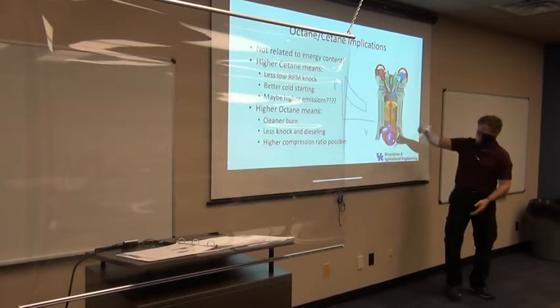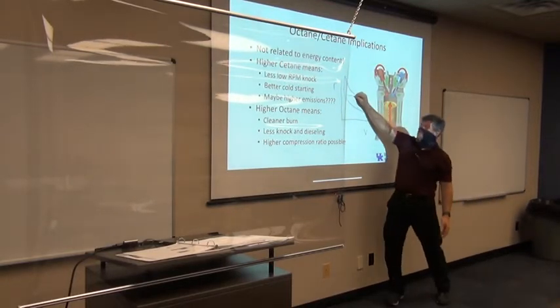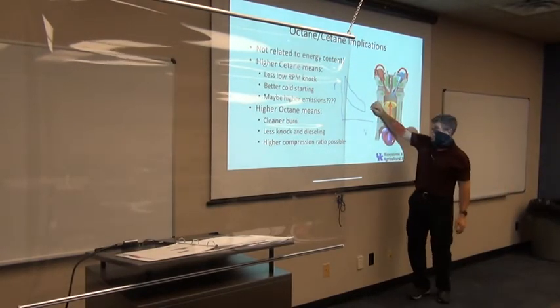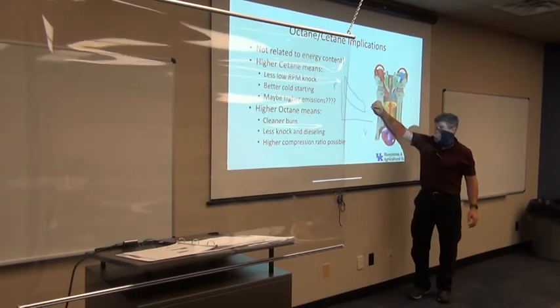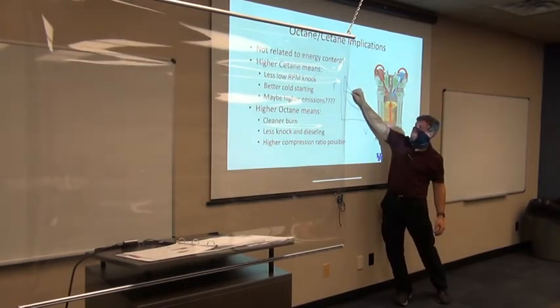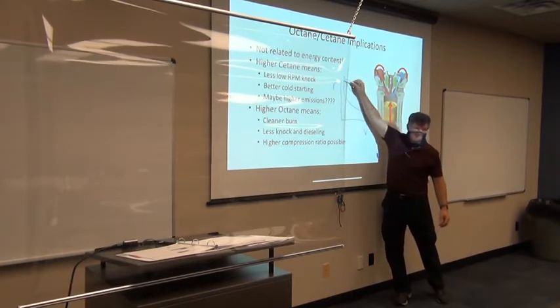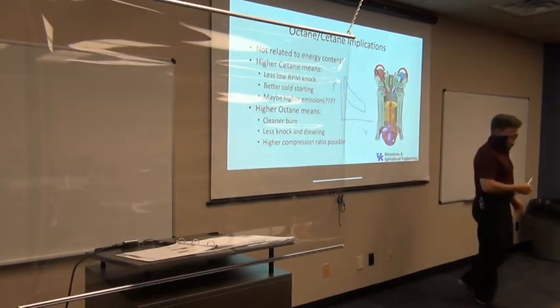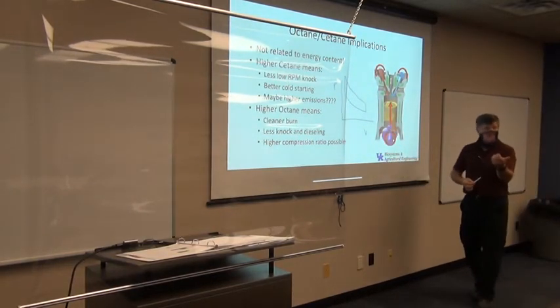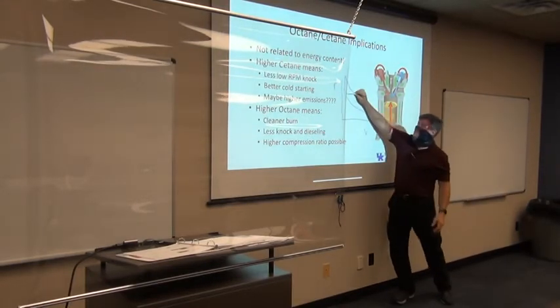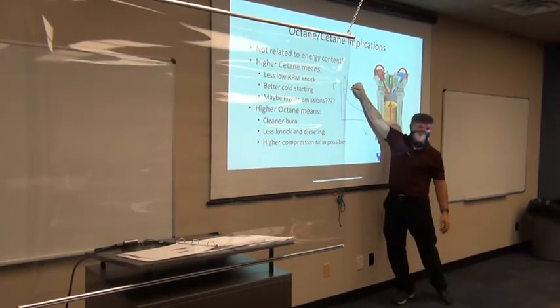New gas coming in. All right, so this stroke, I start from here and go up to here. Which stroke is that? That's the compression. I've already had the intake, the fuel or air-fuel mixture, depending on what kind of engine I have. I compress it. I get to here, then I get this big pressure spike. That should be a vertical line, I really drew that poorly. That's when I've ignited the fuel, either injected it or lit it with the spark, and it burns. So that's really ignition in here.